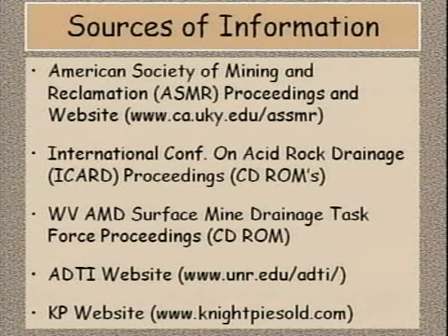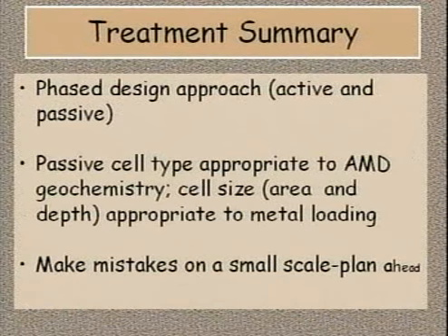So, what did we learn in the treatment segment? You can treat ARD either actively or passively, and using a phase design approach of lab, bench, and pilot tests can significantly lower the risk. In this way, you tend to make mistakes on a small scale. And you need to know the ARD chemistry and the loading to size the treatment system.